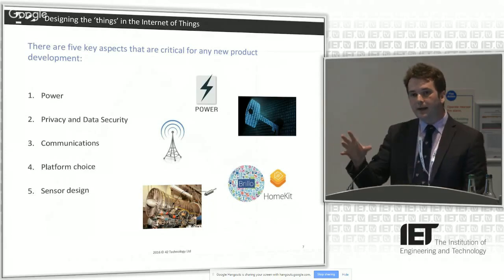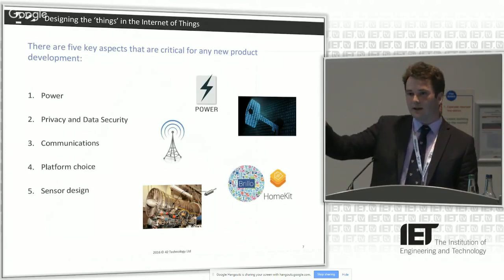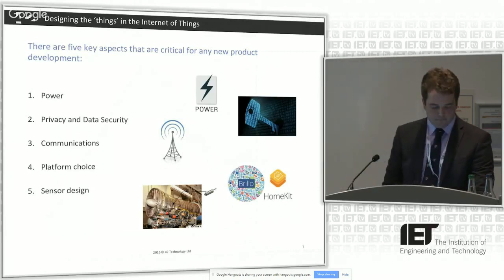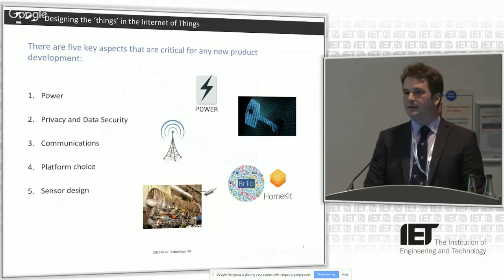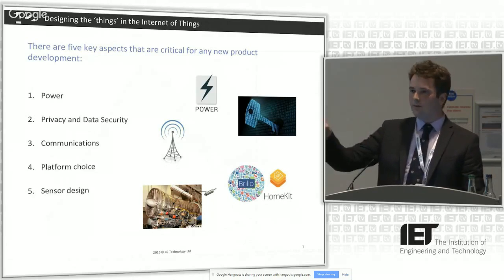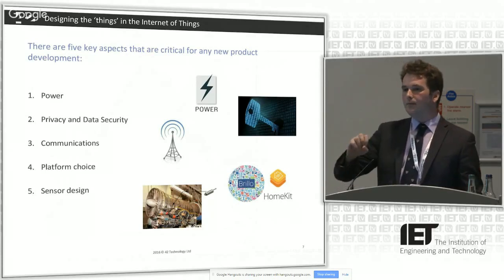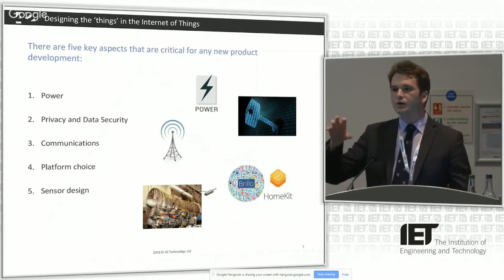Effective data transmission optimization is also important because sending information is expensive. And there's always a trade-off to be made between doing onboard computation to send a small amount of data and just pinging data up to the cloud and then maybe doing the processing up there. And every design device choice that's made affects battery life to some extent. We're getting to a point with some battery technologies where we can almost say this number of computational steps consumes this much energy. This kind of wireless communication, depending on where you are in the world, what technology you're using, costs this much energy. And you can then start to budget.